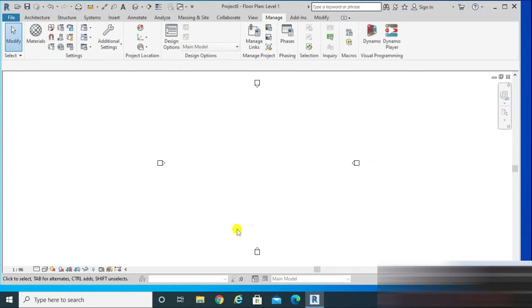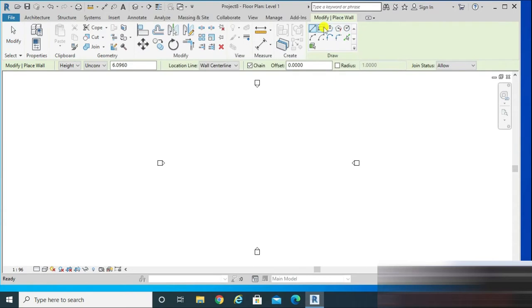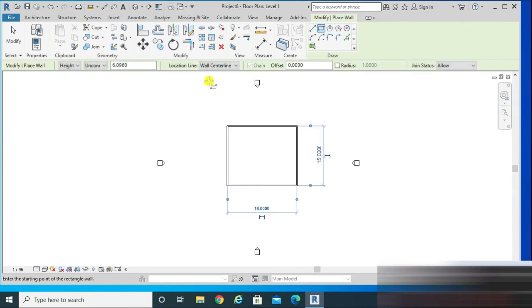Now we are able, for example, to create a wall as an element. Please note that the first interface that appears is called the option bar, and this is its location. Additional options appear when we are in the middle of creating an element like the wall.